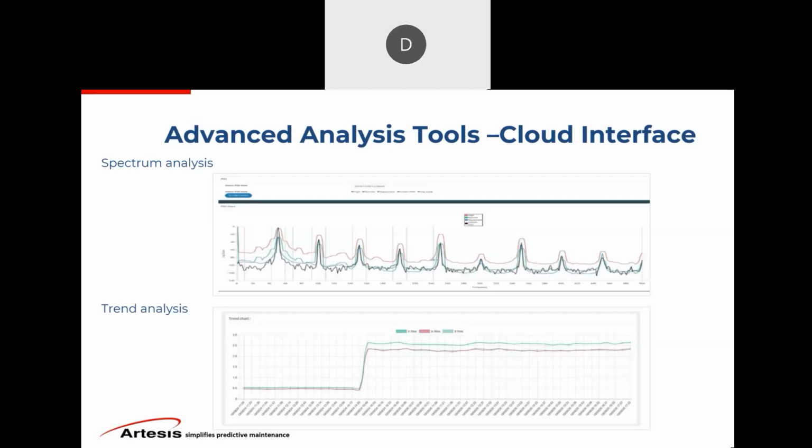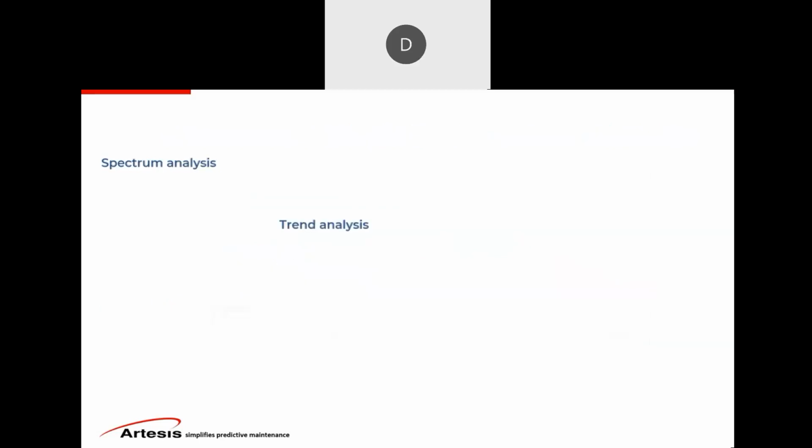The bar graphs that I showed in the previous slide are the rolling average of 3 days of data. So those bar graphs will creep up slowly because we capture things so early, and we don't want to give a lot of false alarms. But if you see that bar graph going up, we can look at the trend of that particular fault. Maybe it's a bearing, and we get a data point every 15 minutes that we're plotting. So now we get a lot more data for that trend, and we can look at it more frequently and see if it is continuing to rise on a daily basis, and maybe it might trigger some maintenance action on that particular machine.